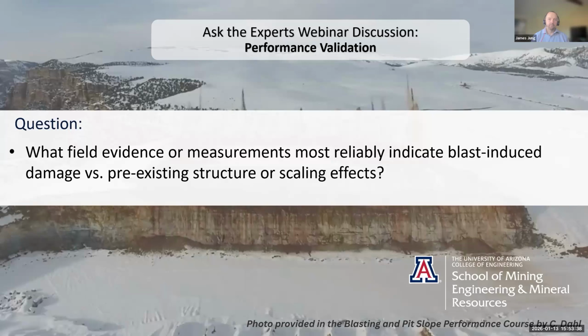And so you know where your natural fracture patterns are, where some of your major structures are, hopefully. And sometimes even when a blast goes wrong, it'll translate energy along a known structure, sometimes even an unknown structure.